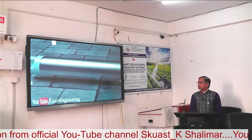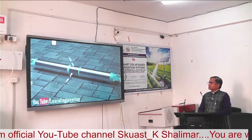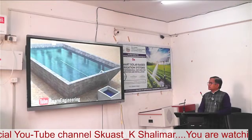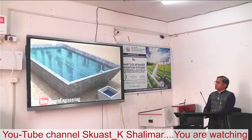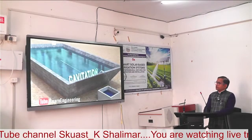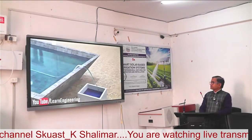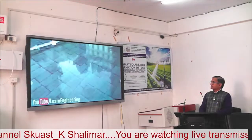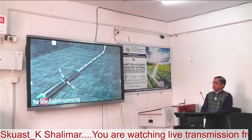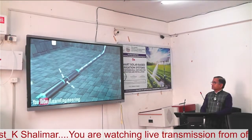The entire impeller motor assembly is immersed in the working fluid. This means that priming is not needed in submersible pumps, as with conventional centrifugal pumps. Another major issue faced by normal centrifugal pumps is the issue of cavitation. So both issues are eliminated: priming and cavitation. One of the main reasons for this happening is the low pressure on the suction side. In submersible pumps, the water is pushed rather than pulled, and this reduces the chance of a negative pressure head in the system, and thus the issue of cavitation does not occur.